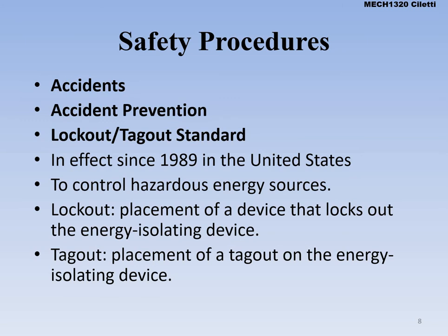Nobody really wants to work on live 480 volt electricity, 3-phase, that's going to hurt if you accidentally do the wrong thing. You're not going to want to climb under some hydraulic press to work on it if it's on. So there are different ways to make sure that it's off and make sure that it stays off, that no one can remove it. So we've come up with the lockout tagout.